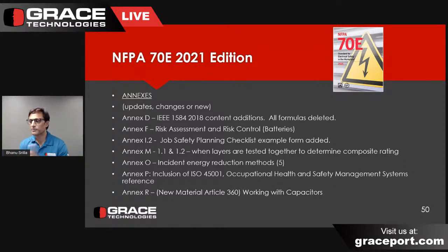Before you skip that, the layers of testing, right? So on the PPE, we talked about this just before we started the webinar. You can't have different manufacturers done together. So basically, you can't have a Westex and then another one as a layer. You need to have them only as tested together. From the beginning, you weren't supposed to, right? From the beginning, you're never supposed to have different manufacturers layered and add the ATPVs.